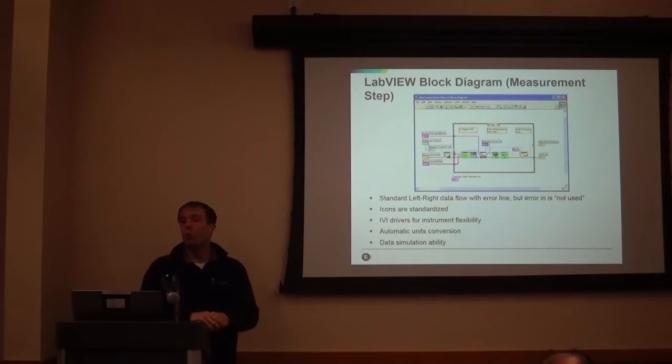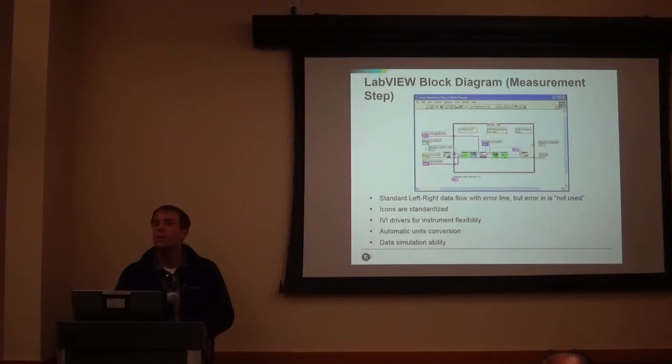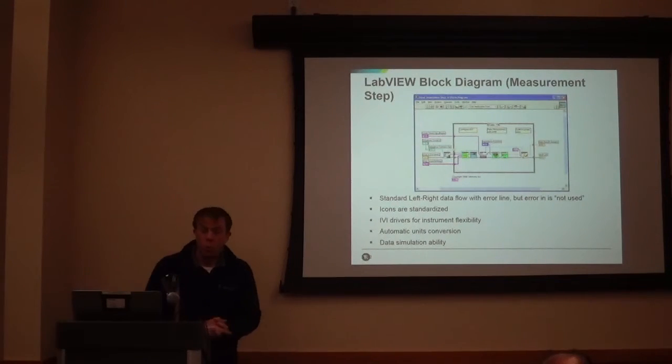But now, if I install something in the C drive, somebody who has access to the C drive can go to the program and then they are able to see and make changes to the sequence file. There are ways to help protect against that. If you're on a deployment machine, like the actual machine that's running the sequence, the runtime can show you the sequence that's being run, but you can't edit it. With a base deployment license, you cannot edit a sequence. So that's the license issue.